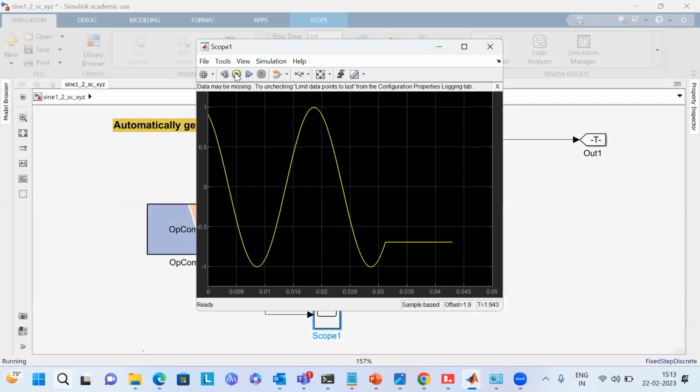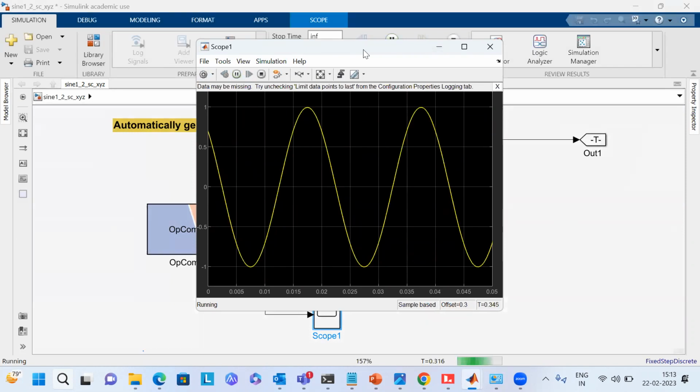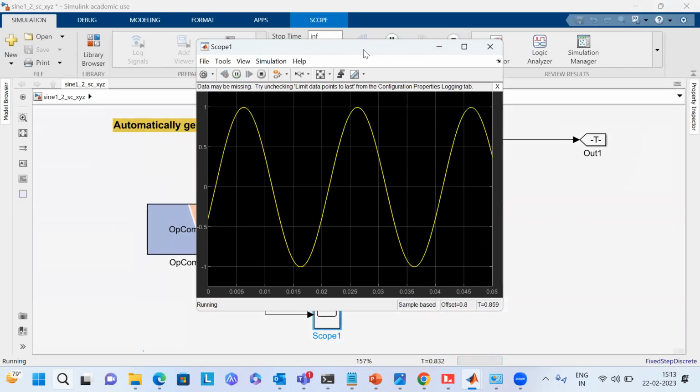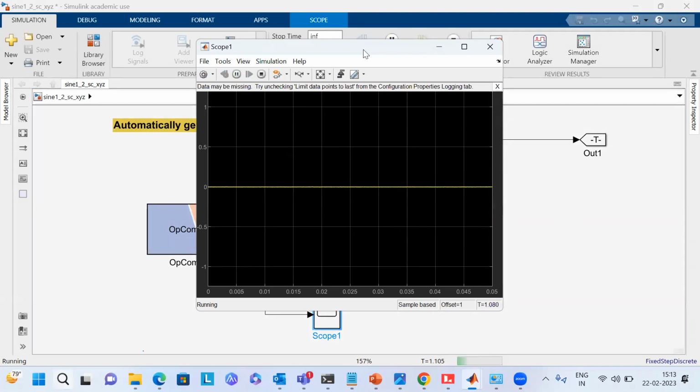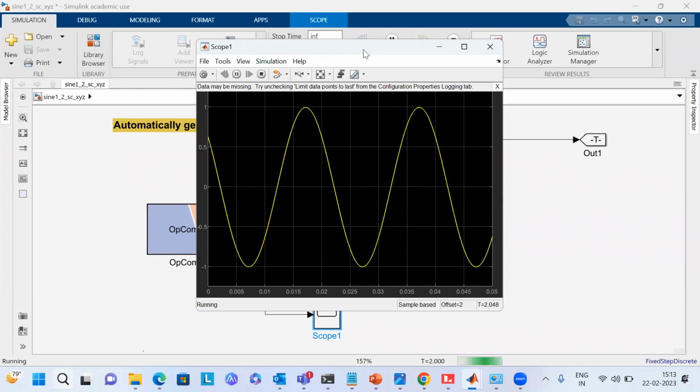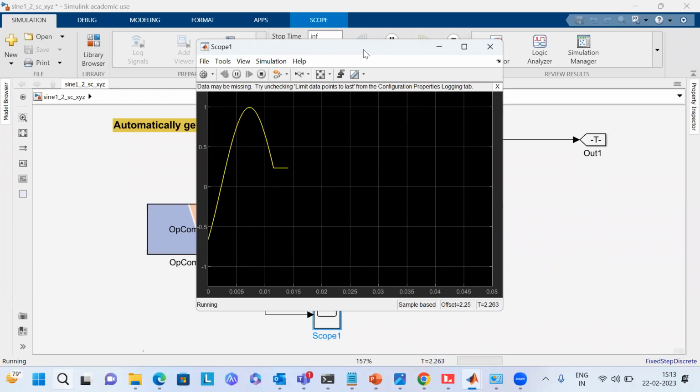So this is your analog input result. We'll take it from that loopback cable. Now I open that loopback cable. Your result is 0. So again I connect this loopback cable.